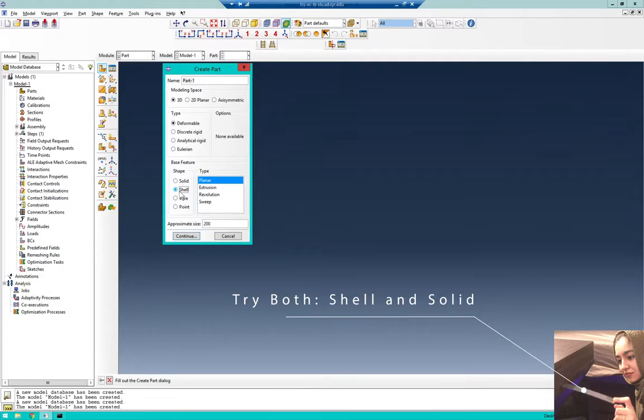over 0.07 centimeter, right? It was 0.7 millimeter, which means 0.07 centimeter. So when we divide them, it's going to be much less than 0.1, right? So we can use thin elements or shell elements here.